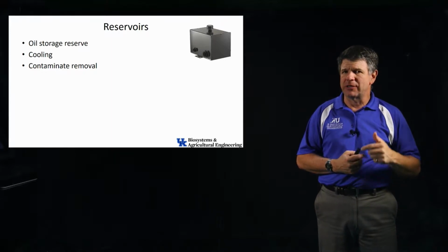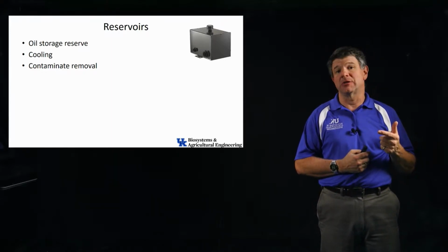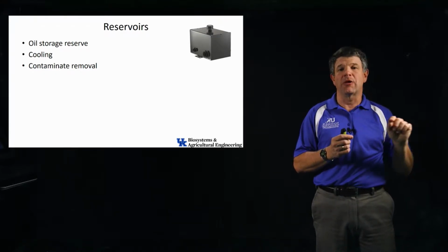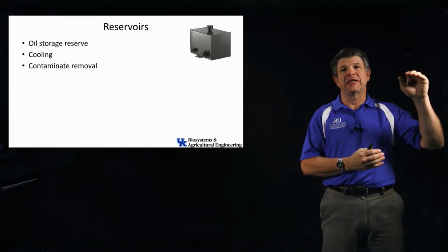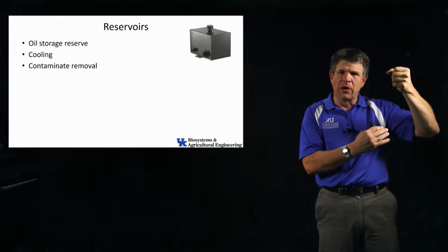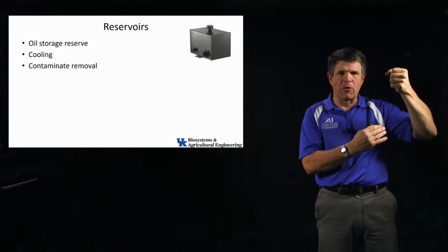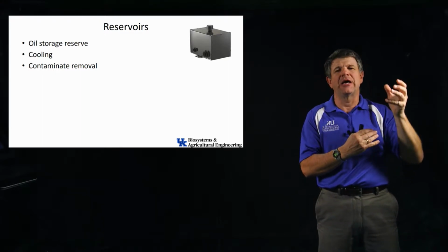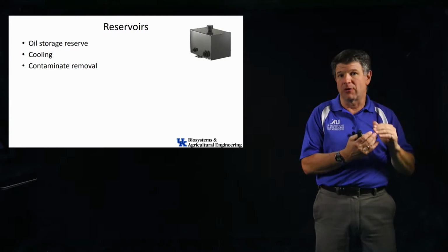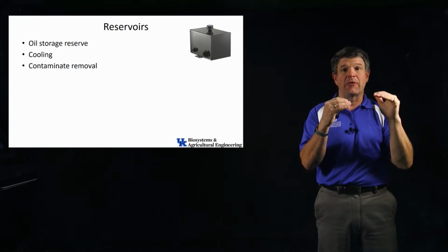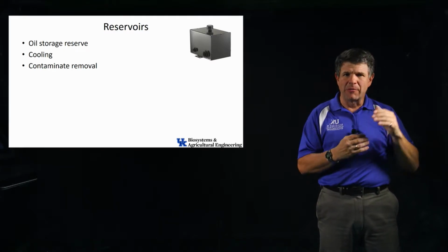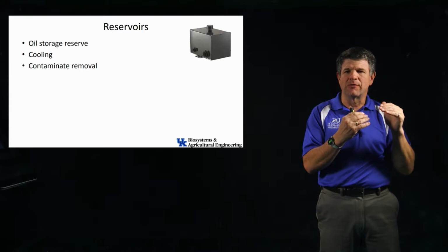But if you think about the hydraulic cylinders that we just looked at, if I'm extending that cylinder, it takes a certain amount of fluid to be able to extend that cylinder. Well, as the cylinder extends, you've got fluid coming back, but think about the volume on the other side of that cylinder. Remember, that rod is in there, so the amount of volume that I displace out of the cylinder that comes back to the reservoir is less than what went out. So if I extend that cylinder, the level of my reservoir actually goes down because I'm taking more out than I'm putting back in. So that would be a case where I've got to have a little bit of reserve in there to make that happen.